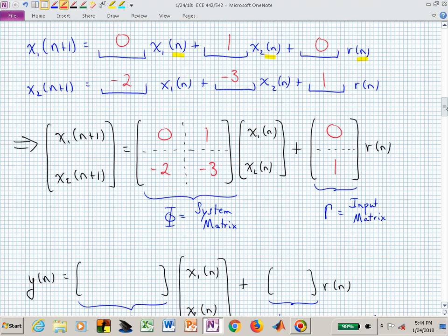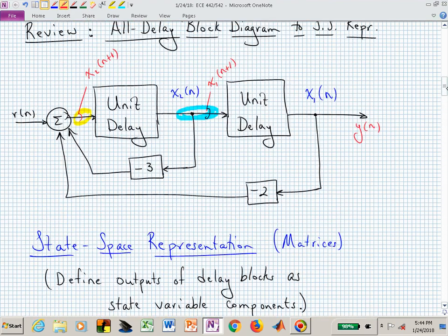And if we go back to the block diagram, we simply look and see y of n could be coming out of a summing junction, and if it was, then it would be all of the inputs into that summing junction. We could put in a virtual summing junction right there and say what signals come into that summing junction to create y of n.